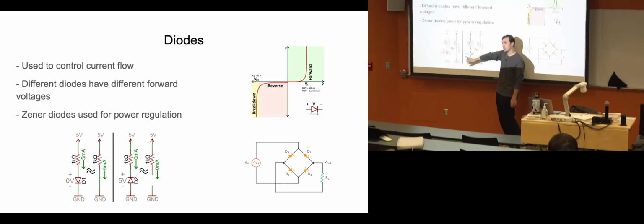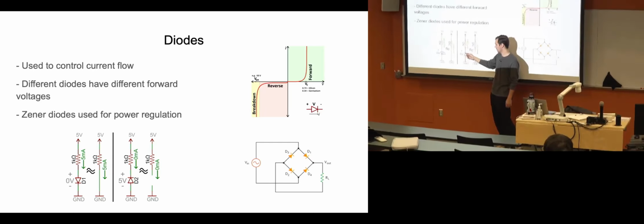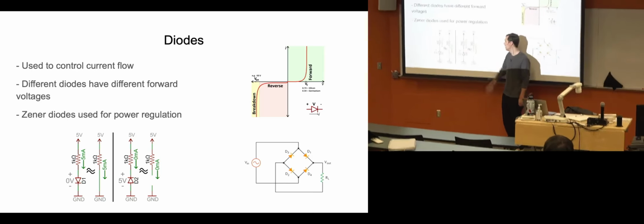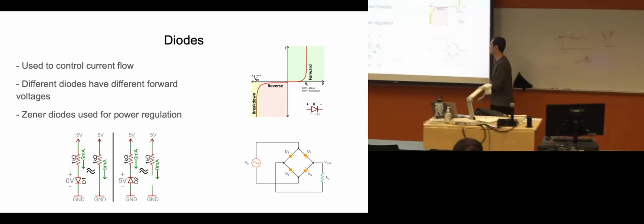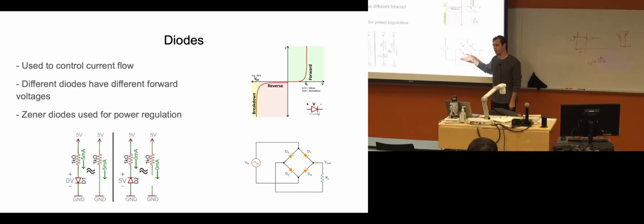In this scenario, we have the diode flipped, okay? And as you can see, there's 0 milliamps going through this because this is blocking it. The current can only flow in one direction. So this is actually equivalent to being an open circuit or high impedance mode, right? So you can do some really cool things with diodes to do voltage rectification, right?